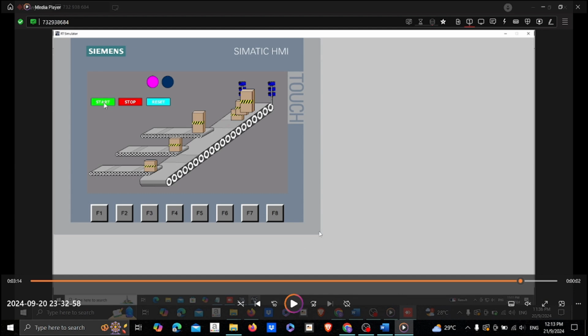The buzzer also will sound with a 2 Hz pulse tone until the reset button is pressed. The boxes will be counted according to their height. If any of the boxes reaches the quantity of 12, the operation will stop until the reset button is pressed. The operation will continue without pressing the start button.